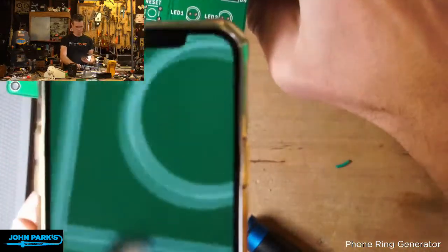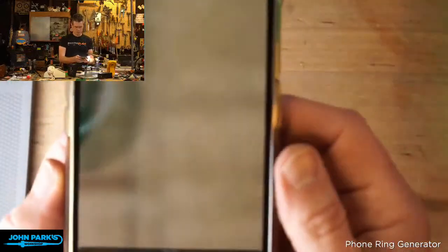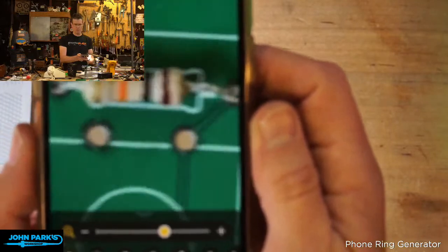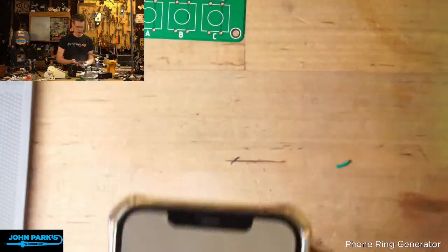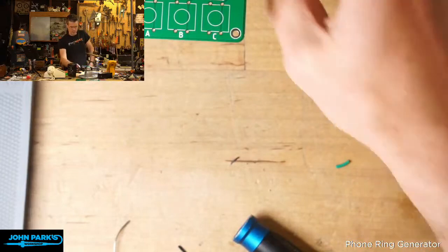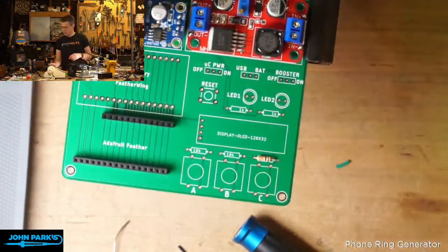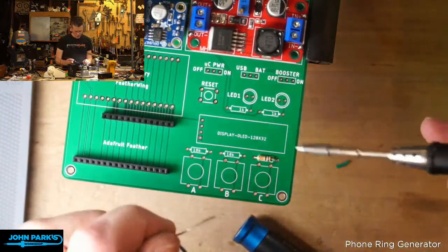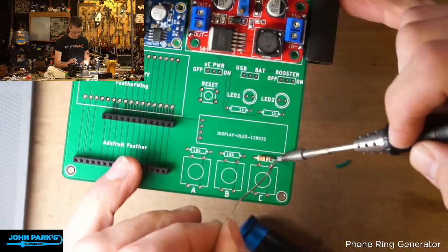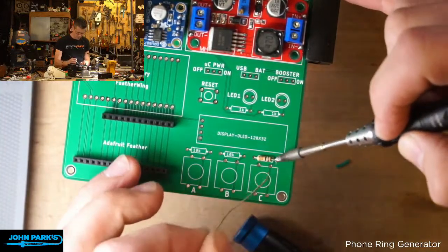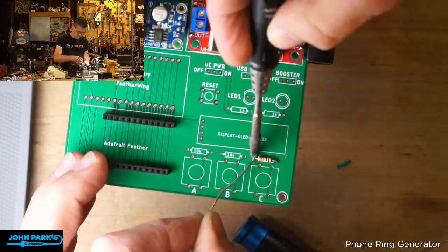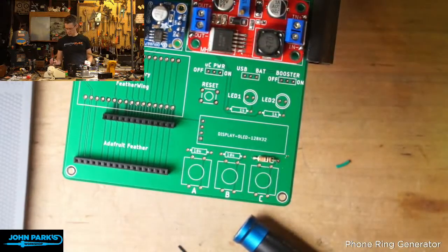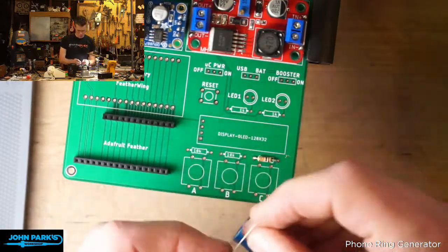Okay, so let's move everything. And there. Can you see that well enough? Yeah, I'd have to refocus. I don't know if that's worth it. Maybe another time. But if I mount the phone on a little mount arm, you might be able to look through that. But just imagine you're seeing a resistor get soldered in place. So I'll do this from the top, just because then I don't have to worry about flipping stuff over. It's a little easier, I find, in some cases, especially for things that want to fall out. These resistors won't, because of how tight the legs are bent in there, but there's no reason you can't solder things like that in from the top. Okay, so that's 10K. There's another.